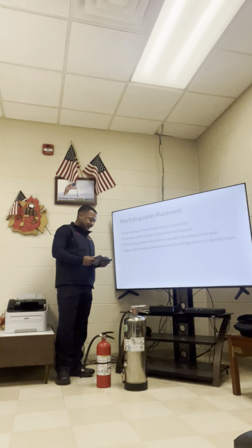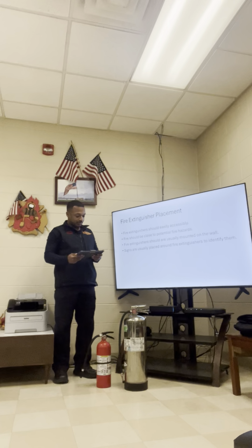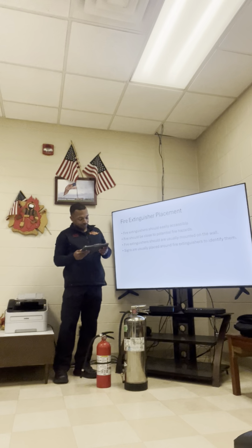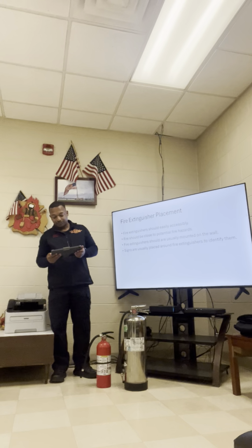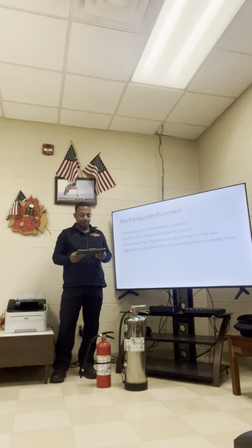Fire extinguisher placement. Fire extinguishers should be easily accessible. They should be close to potential fire hazards. They should usually be mounted on the wall. Signs should be posted where you can find the fire extinguisher and identify what type of fire extinguisher is being used.